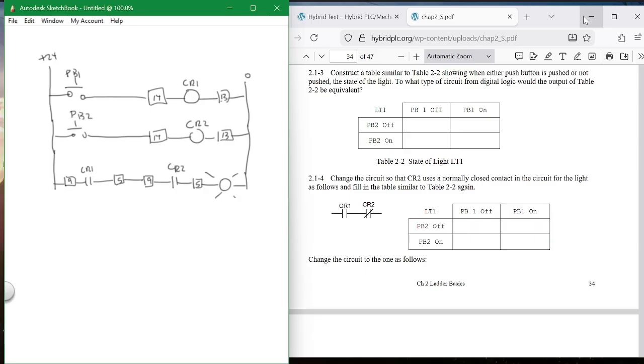In a way, even though it's not theory, you just got hammered just a little bit with this one little thing about relays. And I hope that you can take that and put it into a lab and then cement that in your head, because that's important. That little seal circuit is the basis for a lot of the things that we do. If you do it, you'll never forget it, okay?